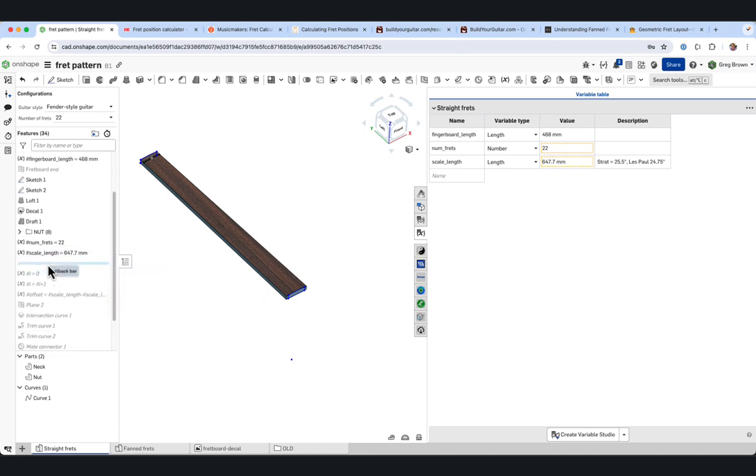The next variable we have to define is going to be called I. Now, I is going to be a loop. If any of you are familiar with programming, one of the most common patterns is a for loop, where you say for I equals 0 to 22, and then you execute a lot of code inside the curly brackets, depending on what you're using, JavaScript, whatever. You execute that whole block of code, where you can use the I, which increments from 0 to something. Now, we can do the exact same thing in the feature tree, and this is not using custom features or anything. We're just going straight normal Onshape here.